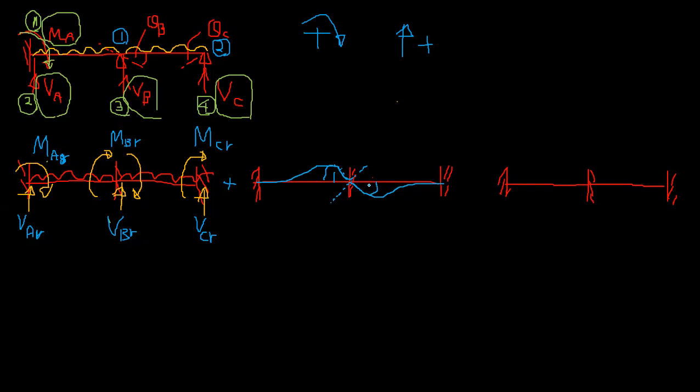This is 1. So you apply a unit rotation. In the force method, you apply unit force, and there you get the displacement per unit force. Here you get the force per unit displacement. That becomes stiffness. That's why you take S coefficients, stiffness coefficients.